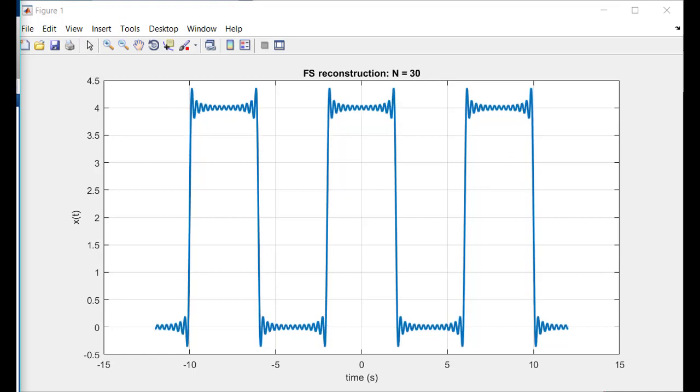However, right at those discontinuous points, you notice that's the largest error for the approximation, and that's called a Gibbs phenomenon. So it will actually remain, and it would never go away unless I could actually do this to infinity. However, what happens is that as it gets thinner and thinner, it will get to the point that the power for this signal will be the same as the power for the original x of t, because those points are now so thin that the power is essentially 0.